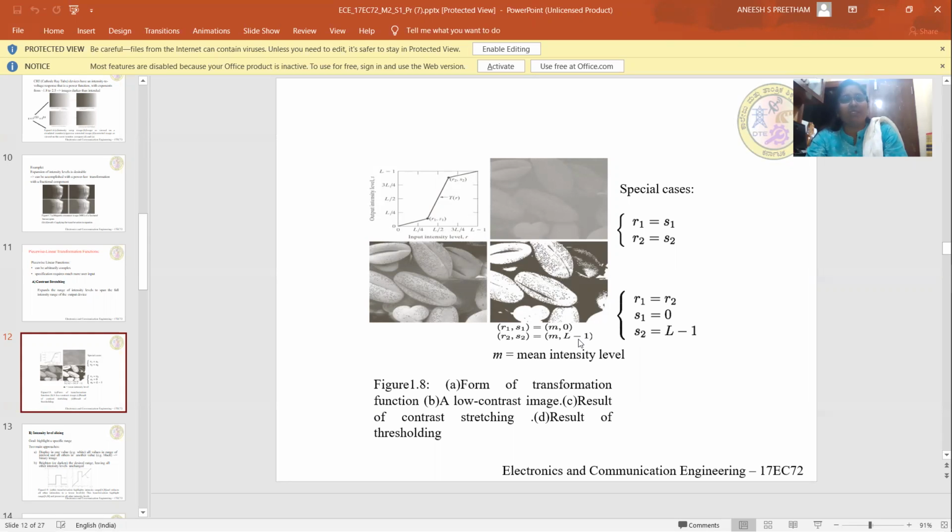So this is a technique which is called contrast stretching, which is mostly useful for images where the contrast is very poor, and we have said that we can get poor contrast for various reasons. Either scene illumination was very poor, or the dynamic range of the image sensor was very, very less, or the aperture setting of the camera lens was not proper.